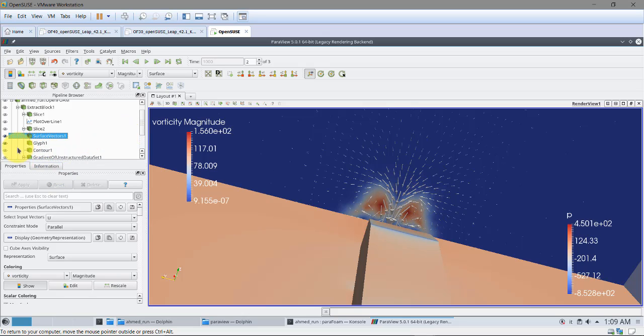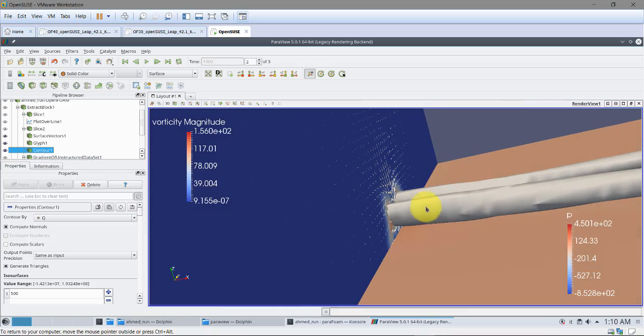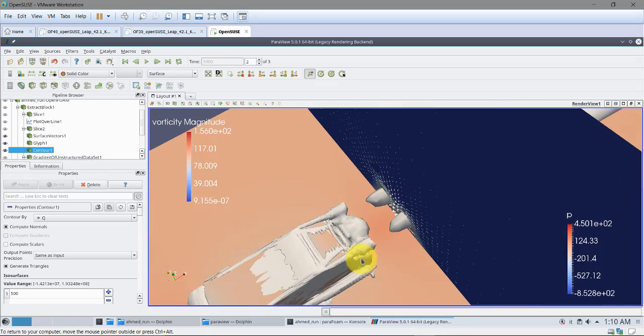And now, for instance, I also have access to the Q criterion that I computed in OpenFOAM, but I will show you how to compute it also in ParaView. So as I plot here, you see that we have those vortices there. They are not very well characterized. Remember, this is a quite coarse mesh, so it's part of your validation as well. Later, if you want, you can go and refine that mesh, do an LES or this.